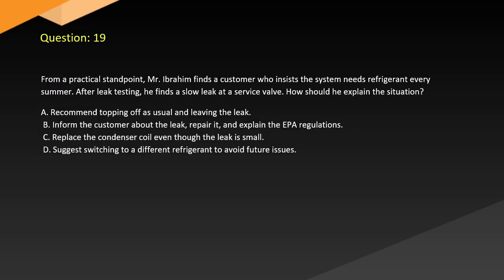Question 19. From a practical standpoint, Mr. Ibrahim finds a customer who insists the system needs refrigerant every summer. After leak testing, he finds a slow leak at a service valve. How should he explain the situation? A. Recommend topping off as usual and leaving the leak. B. Inform the customer about the leak, repair it, and explain the EPA regulations. C. Replace the condenser coil even though the leak is small. D. Suggest switching to a different refrigerant to avoid future issues.